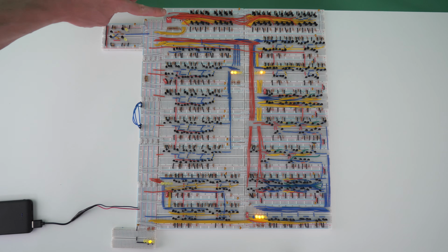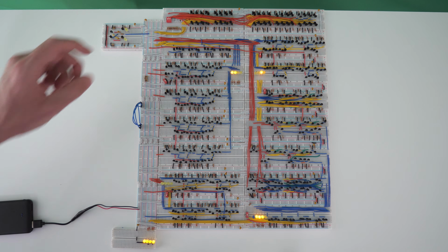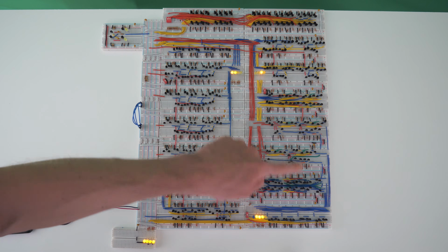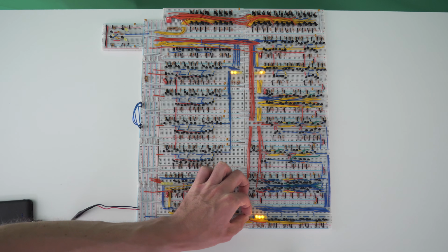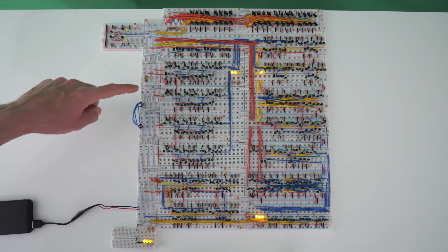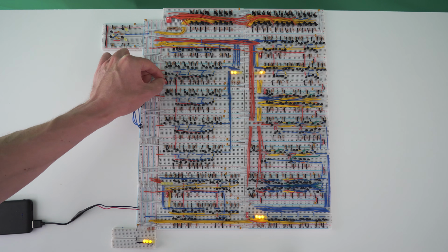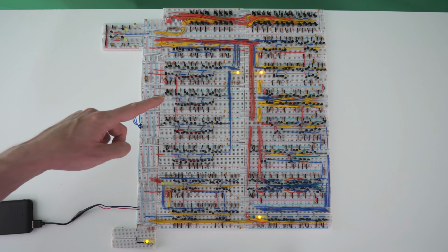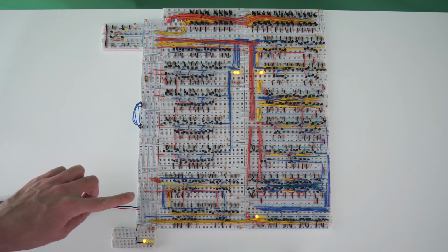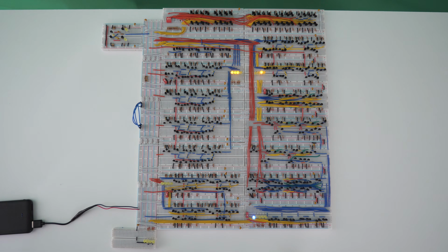We want to make it so that our memory is no longer connected to the data bus, so we will turn this off. And now we actually want the ALU to be continuously connected to the data bus, so we will flip this switch right here to do that. And now we want the data bus to be continuously connected to register A, so we can do that by flipping this switch right here. So now our computer is actually incrementing by 2. I also want to show this output in our output register, so I'll flip this switch right here. And now we can see that the computer is counting by 2.